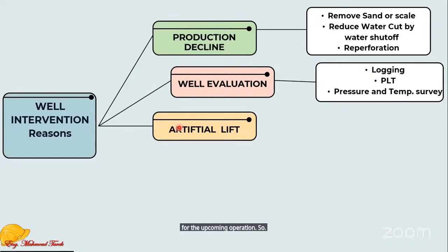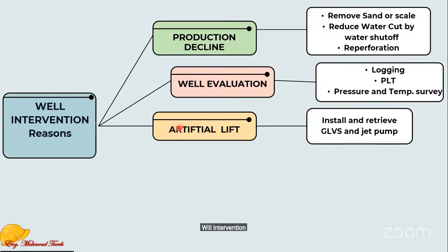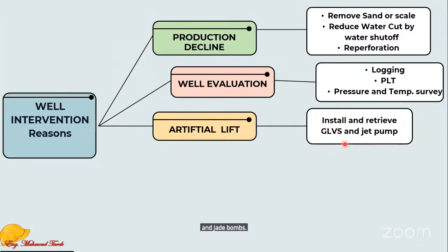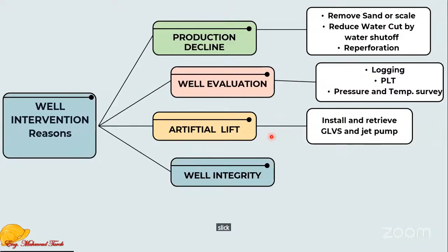So another interaction and a reason for the well intervention: the artificial lift. What is the intersection between well intervention and the artificial lift? We can use some tools, as we will see, for installing and retrieving gas lift valves and jet pumps. Those artificial lift techniques can be replaced and maintained by well intervention, especially slickline, as we will see.